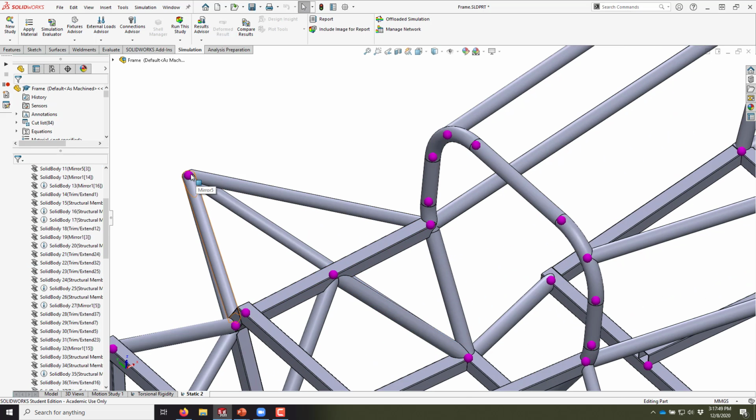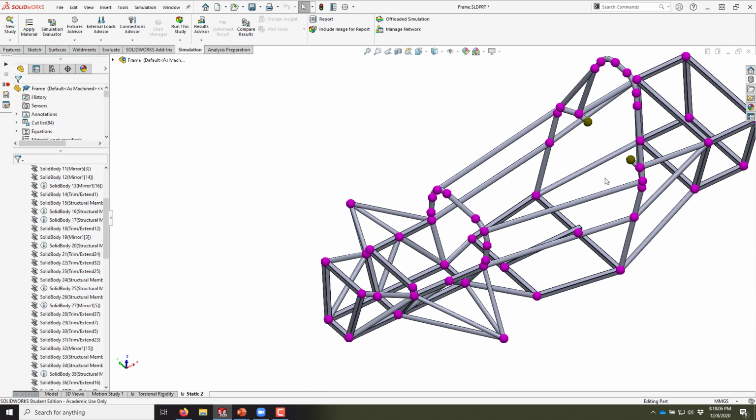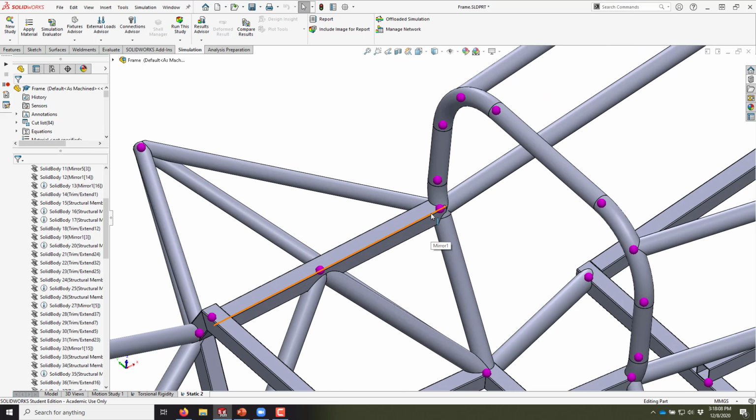This is like my suspension. These are going to be bolted, but they'll be pinned, so they'll have some freedom to move about a little bit. But everywhere else there's going to be welds. So I want to treat these joints that we see in these corners a little differently than all the other joints. I want to treat these more like pinned joints.